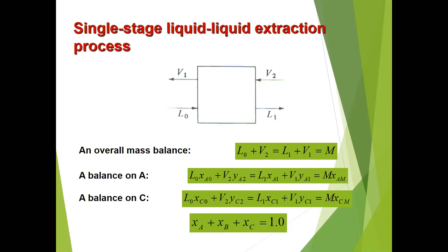And now for this afternoon, we will be discussing a liquid-liquid extraction, wherein this time we will really have a feed, which is our L0, and it will be contacted with the solvent V sub 2. Now resulting in the equilibrated phases, the extract, which is V sub 1, and the raffinate, which is L sub 1. So these two phases are equilibrated.